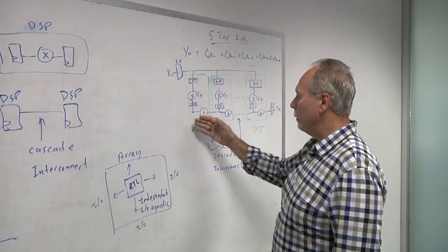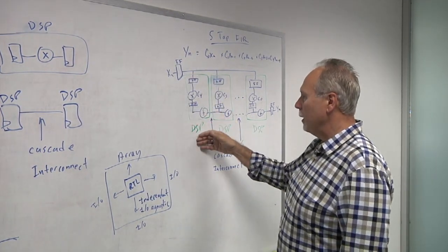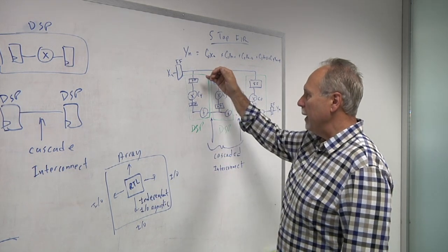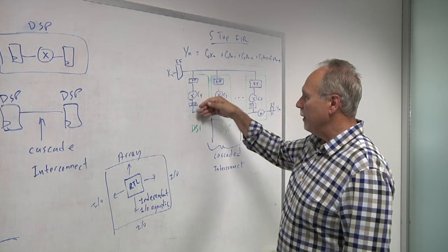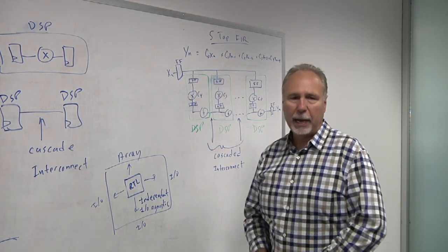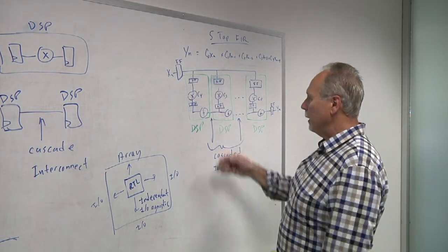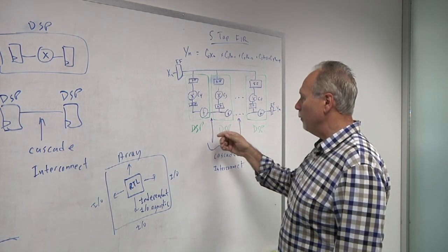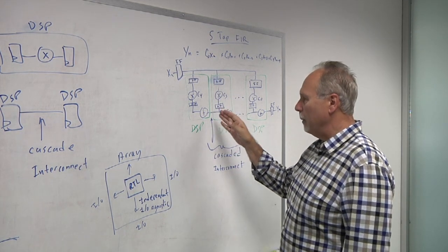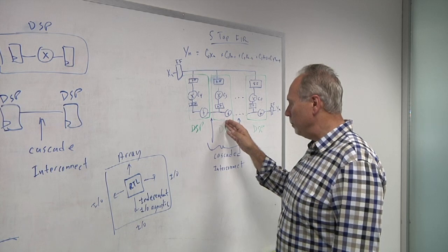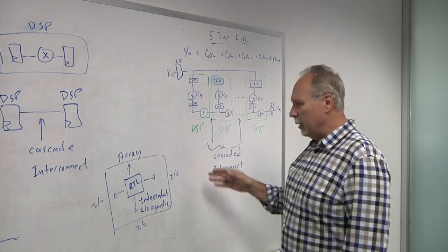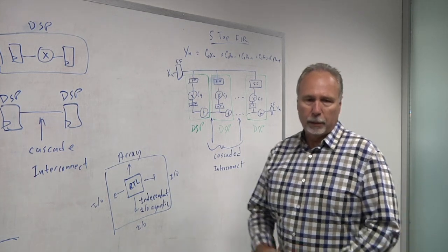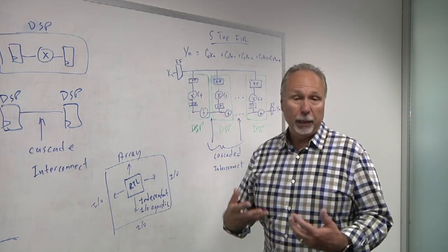So if you take one element, for instance, we call it a DSP, it might have a flip-flop to flip-flop path and a multiply. So the speed of that path is one aspect of performance. Then there is another aspect of performance: how fast can I get from one DSP to the other DSP? And you could do that in 2 ways, and that depends on the actual embedded FPGA capabilities.